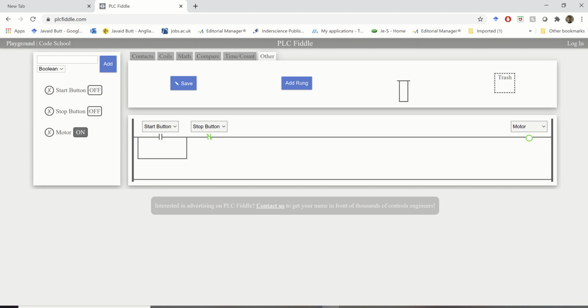This right here is used for branch circuits, as we have discussed. So we already have a branch circuit over here. The way this option works could be a little bit tricky, especially if you are not familiar with how to deal with this. What we have to do is drag this item and place it before or after a specific item in order for this circuit to work.